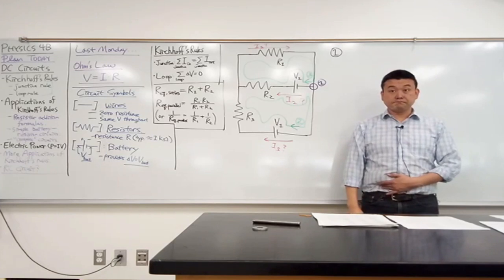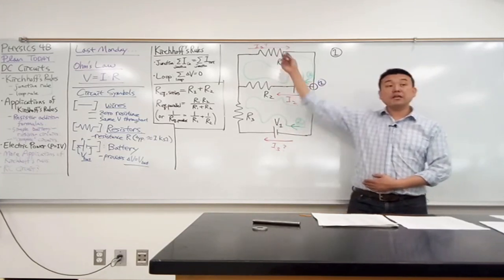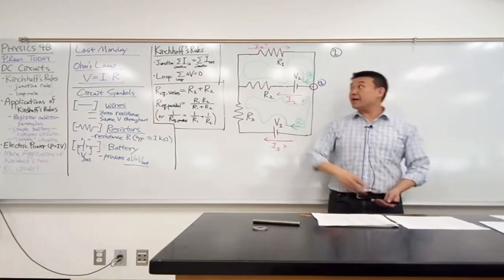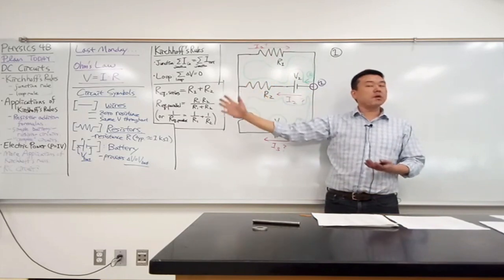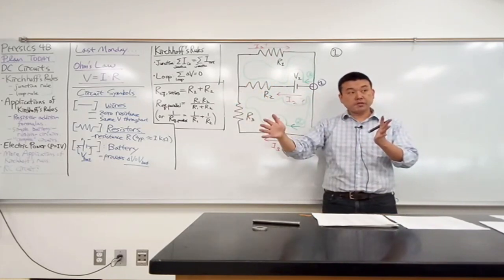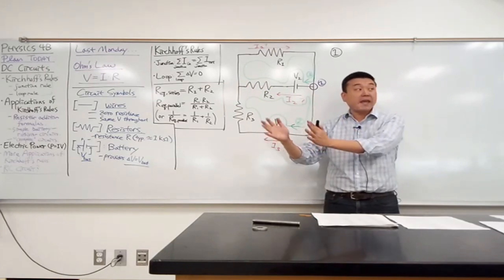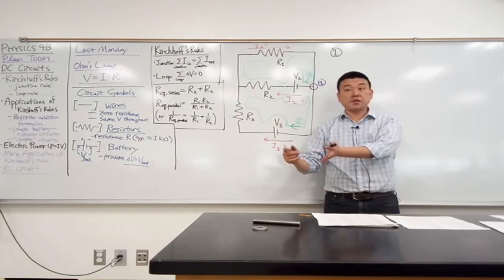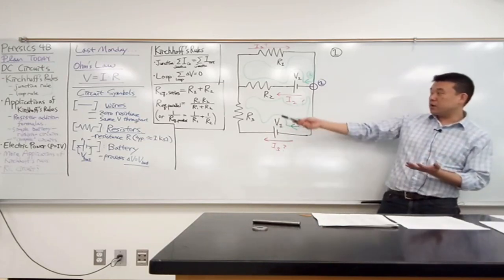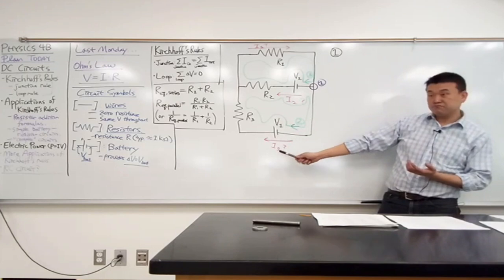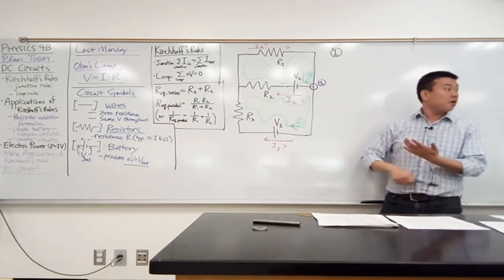Maybe you can label it and use the signs later to... Yeah. So with the direction of currents, that's actually going to be true in every single case. I could have labeled I1 going the other way. And as long as I follow a consistent set of rules, the result I get will be correct. And when my final answer gives me negative current, that'll be my indication that I should flip the actual direction of the current. So here, even though I don't really know the actual direction of I2 and I3, I labeled it some way.